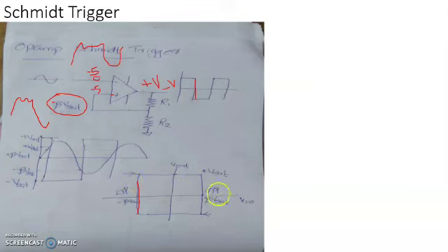So the input-output relationship will be a curve like this. Now there is a delay of input-output voltage when the output is returned back to plus V saturation, or say back to minus V saturation, when we make a comparison at the instant it makes a change of output status.